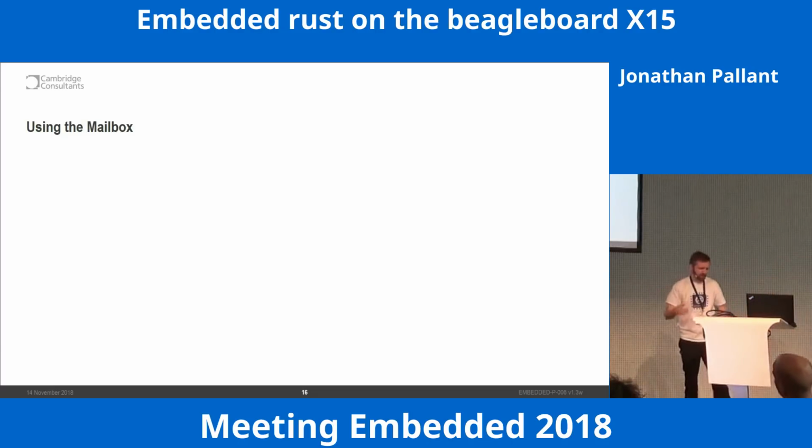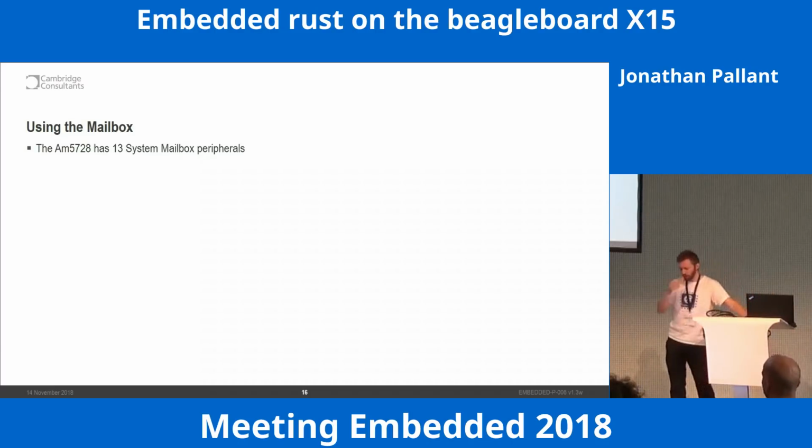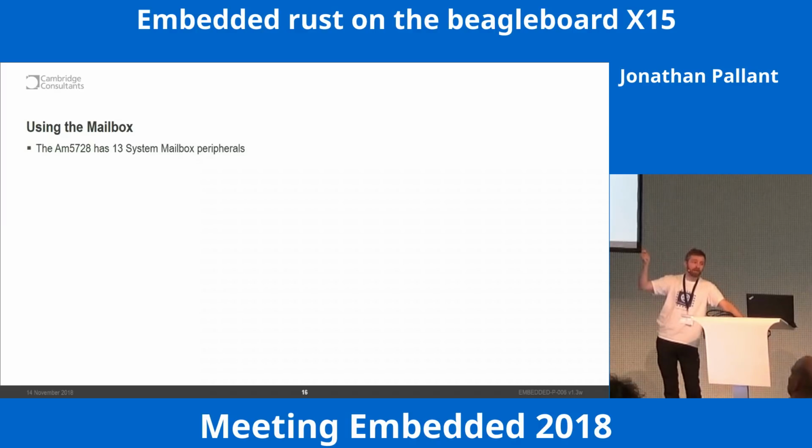So I said interrupts. Well, the way the interrupt system works is there's actually a mailbox. And the mailbox is a lot like an American-style mailbox. You can put things in it and set a flag. It says, yep, mail has arrived. And then the other processor can look and say, ooh, the flag's up. I will go and fetch the mail. And the mail can be one 32-bit value.